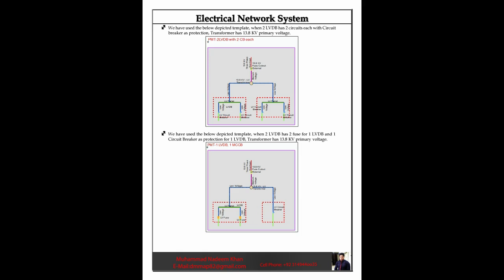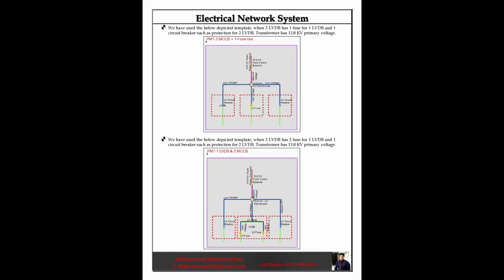We have used the below depicted template when 2 LVDB has 2 fuse for 1 LVDB and 1 circuit breaker as protection for 1 LVDB. Transformer has 13.8 kV primary voltage. We have used the below depicted template when 3 LVDB has 1 fuse for 1 LVDB and 1 circuit breaker each as protection for 2 LVDB. Transformer has 13.8 kV primary voltage.